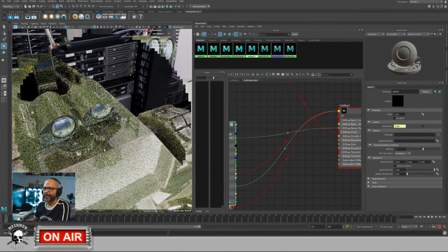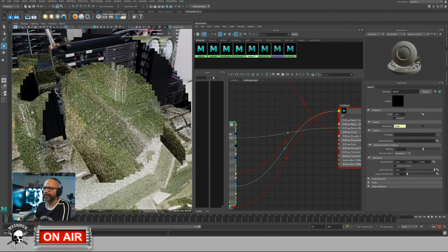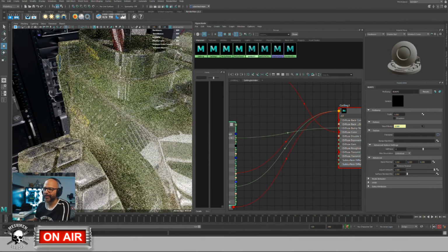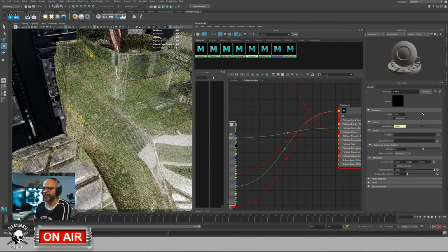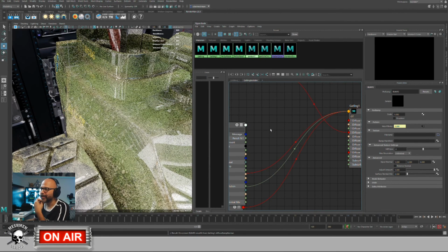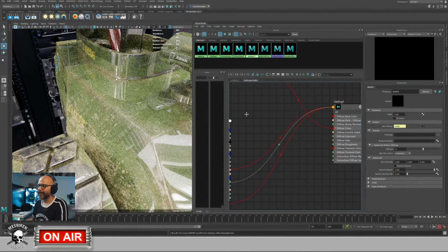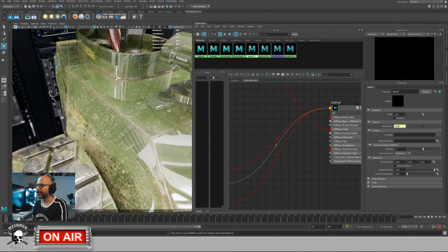You want to, you know, have like a lacquer on top of something. So you want to bump individual components with different types of bump. It's not going to be as visible now because a lot of this is essentially hidden by the specular reflection here. But if I now break this one and take my specular instead, we can see how that reacts. So then I will only apply this bump onto this clear coat here.